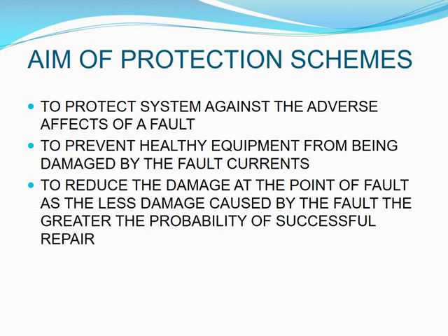So if a fault is happening on a cable and that cable is going, let's say, to a motor, we want to make sure that we are at least protecting the motor by ensuring that we prevent that fault getting into the motor. We need to isolate that cable as soon as possible.